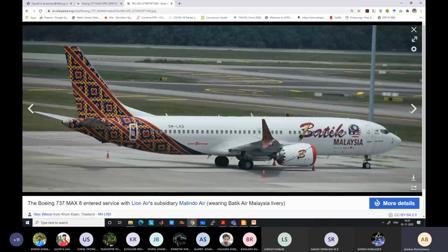Okay, so there is a long history behind this. That's why you will see that many Boeing 737s were grounded after a couple of accidents. 2-3 accidents occurred with the Boeing 737. It has not directly to do with the unstable nature here, it has to do with a software bug, because the software was not allowing the pilot to take control in certain situations. But the software itself was designed to overcome that instability, because of putting in the turbofan engine. So there is a long background history to this, because the engine was changed from turbojet to turbofan in the Boeing 737.